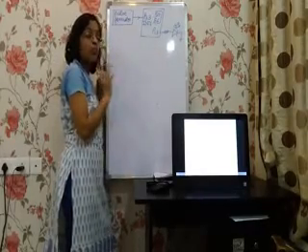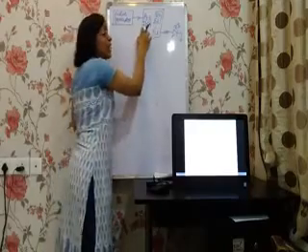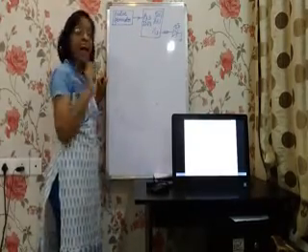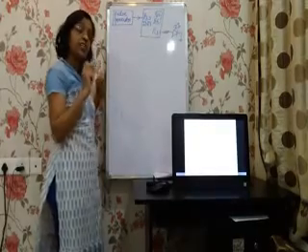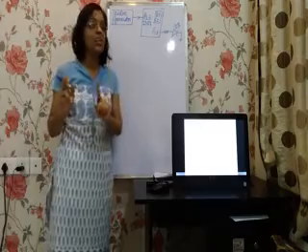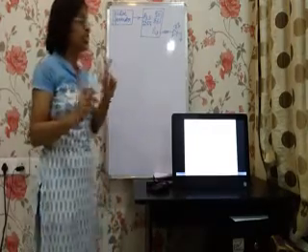For this, first we need to define INT1 as an edge triggered interrupt. And this is the program for interrupts. For interrupts, we first need to enable INT1, so we need to configure which register? The IE register.